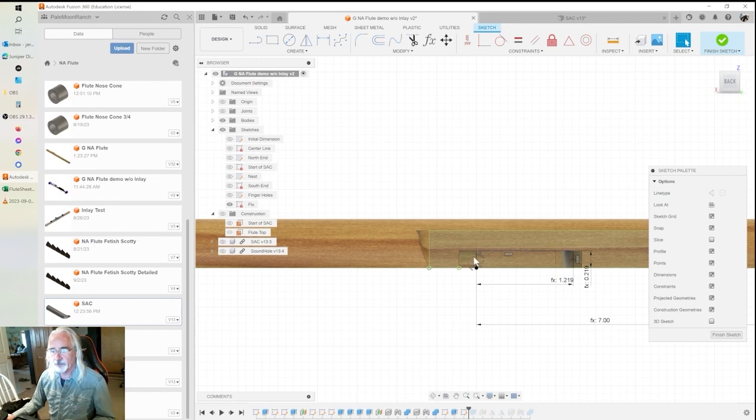So I've set that here, and I've given the flue a length of the flue length, but I've added on the sound hole length to get it past the edge of this hole here. I wanted to make sure I got a clean cut on that. And it's constrained to half the width of the sound hole width. Half because, again, we're modeling only half of the flute.